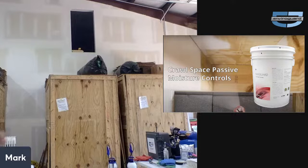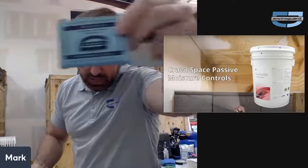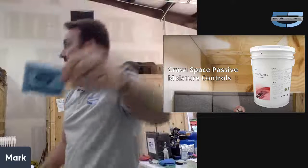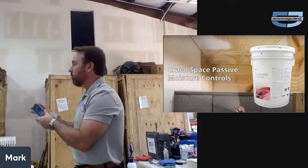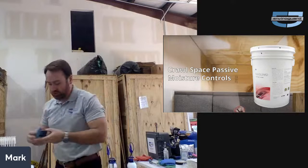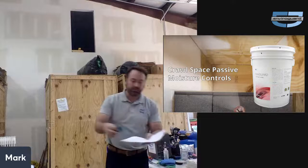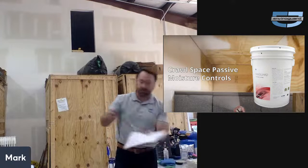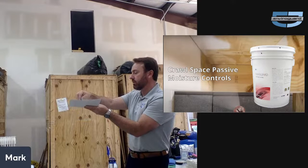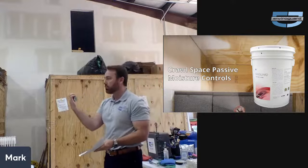So this is called a wet mil gauge. And for anybody who is seeing this for the first time, a wet mil gauge has teeth on it, and those teeth tell us the wet millage that's on the surface. So naturally, the way that it is used is, if this piece of paper is our surface, then we can apply the coating to the surface, tap it to the surface, and know exactly how many wet mils we have on there.